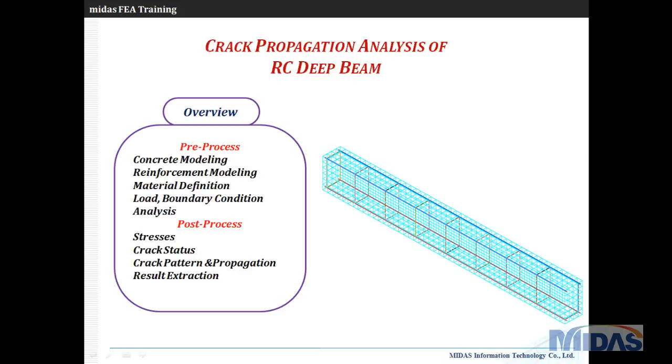In this video demonstration, we will be discussing how to model an RC deep beam for the concrete crack propagation analysis. We will initiate by modeling the concrete beam and the reinforcements, both the top and bottom rebars along with the stirrups, defining the material properties, defining the load conditions and the boundary conditions, and setting up the analysis case. And in the end, we will have a look at how to extract the stresses, crack pattern, the status and the propagation phenomena within the reinforced beam, and how to extract the results in the form of a load deflection curve.